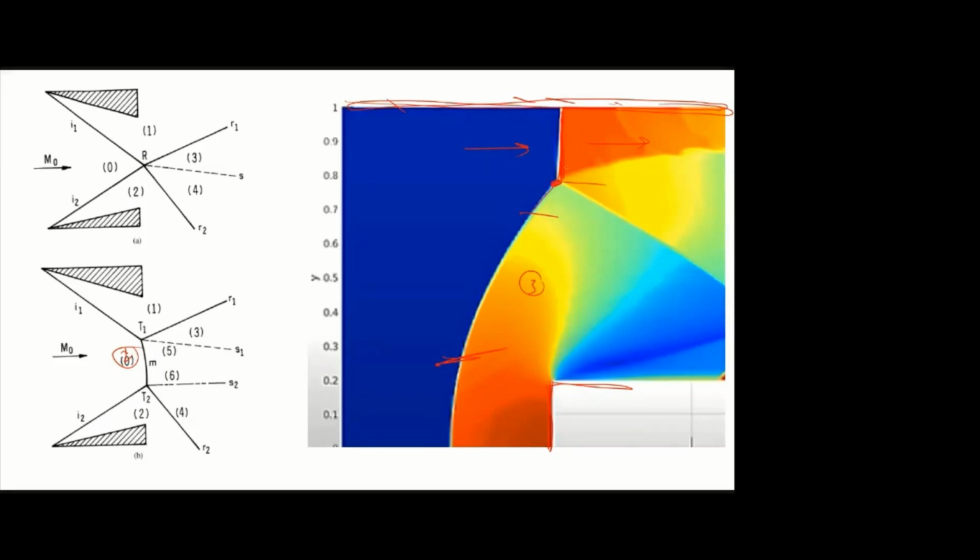From the weak oblique shock wave point, flow adapts and creates a normal shock wave, and from the intersection we are getting another oblique shock wave. Now the flow changes like this. It is straight to this wall. Here also normal shock wave, it is straight to the wall, and here it is subsonic, here it is supersonic. So there is a slip line. So here different parameters, here different parameters, Mach numbers. I think pressure this is.